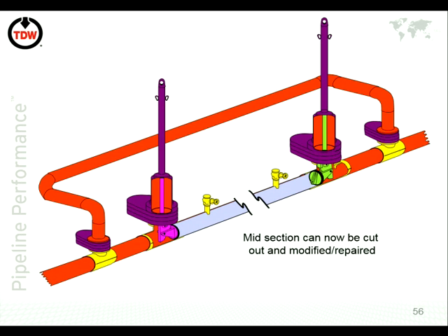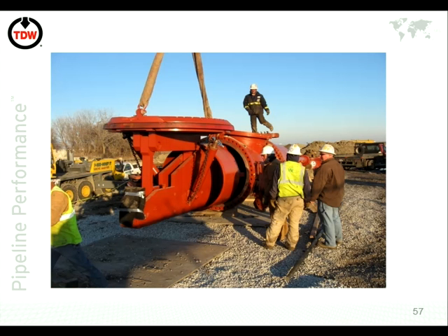These are just some of the big examples of plugging heads. So this is a stopple as it would sit in the pipeline. That is the pipeline diameter that it's going to seal on, and obviously this is the diameter that it would bolt onto. So that's just an example of some of the large sizes that you would use. And this is just a section through a pipe showing you as it drops into the pipeline. This is a wheeled arrangement here, so there's actually a wheel that sits on the bottom and it forces it into that angle.